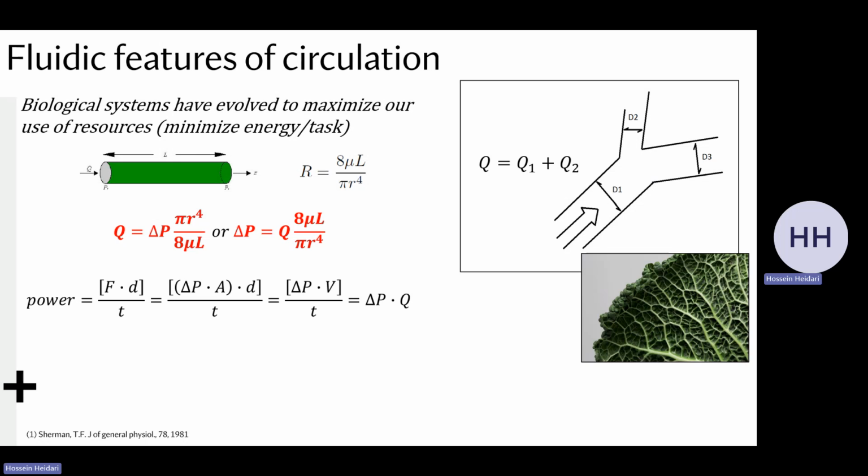I'm going to look at this term called power. Okay, so this is the energy. Again, we'll talk about energy now: energy that's consumed due to these frictional losses, the viscous losses in that channel. And this energy over time, which is power, is the product of force times distance traveled, over time. In physics, you usually do d over t as v, so it's F dot v. But here we just do F dot v over time.